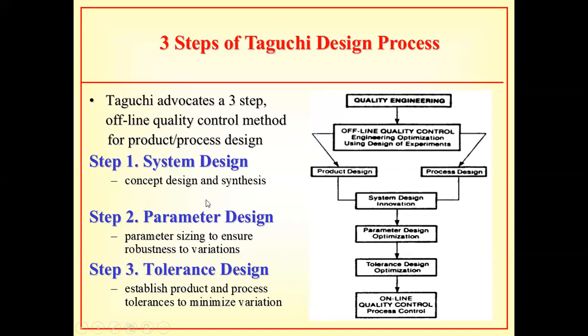But in the second step, parameter design, people were using it, but not properly. They would say, okay, this product has three components. One component requires drilling, one requires milling, one requires turning. So they say, focus on the specification, do this turning. If it is not working at 300 RPM, work at 400. They were basically doing it randomly, trying to meet the specification rather than focusing on the design. Their only focus was to meet the specification irrespective of whatever the RPM is. Because of that, there was product to product variation. Some products are manufactured at 300 RPM, some at 400 RPM, some at 350 RPM.